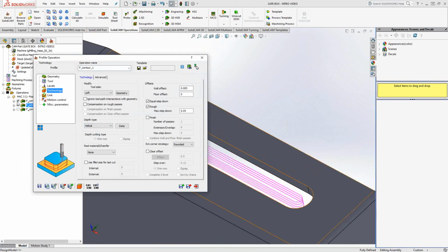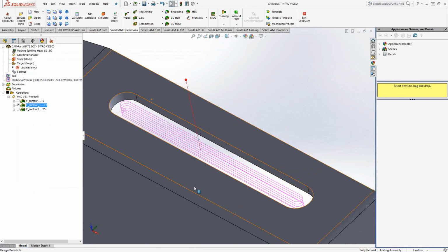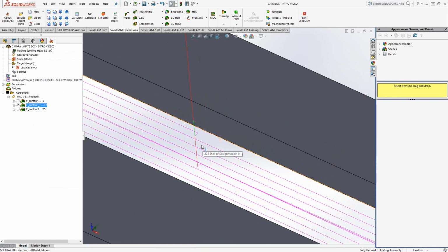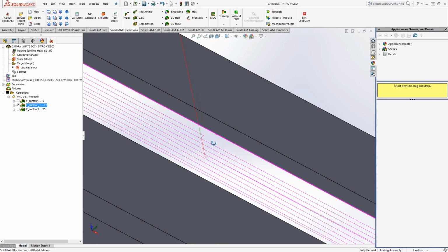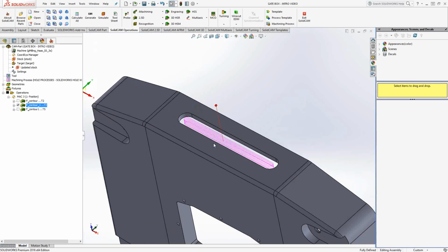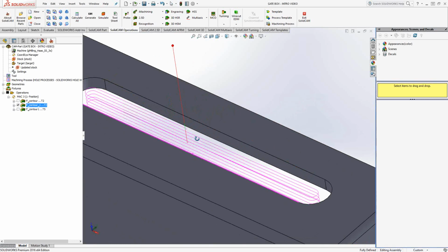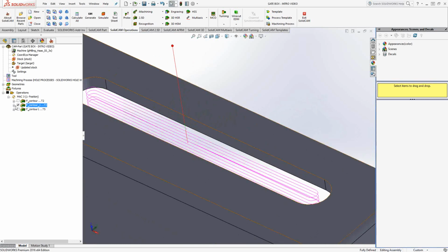And let's take a look at what that looks like. There's no retraction. There's no feeding plunge. Basically, with each lap, it'll do the first depth of cut. So there's a constant Z action, which actually pulls the tool in there. It's a much more accurate toolpath. Okay, so you have that option there.